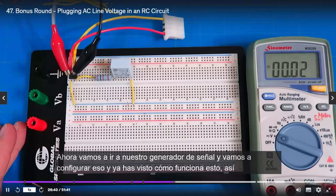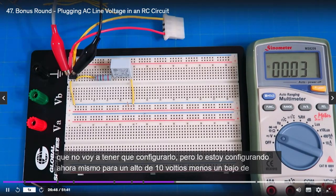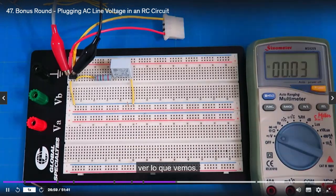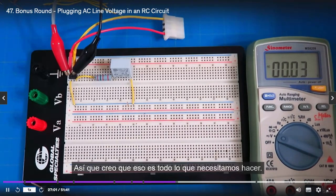Okay. Now we're going to go over to our signal generator, and we're going to set that. And you've seen how this thing works, so I'm not going to belabor setting it up. But I'm setting it up right now for a 10 volt high, minus 10 volt low, so it's a 20 volt peak to peak at 60 hertz, and I'm going to turn the thing on, and we're going to see what we see. All right, so I think that's all we need to do. Let's go ahead, let's turn it on.